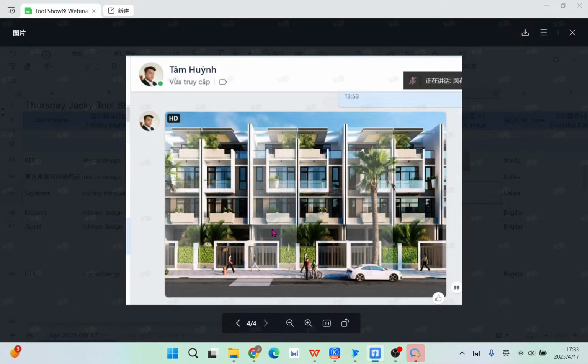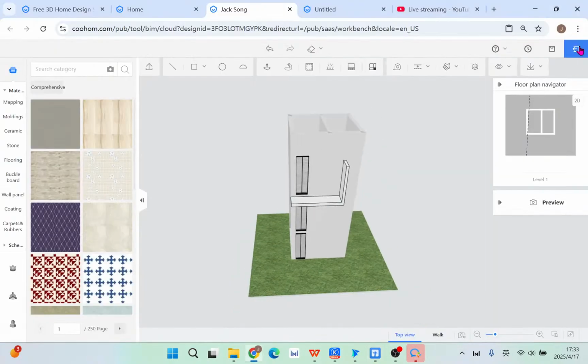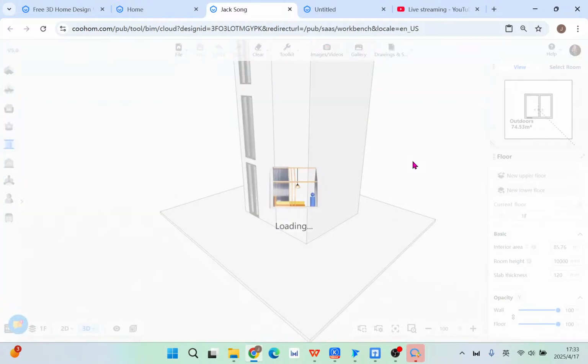Okay, so these are my suggestions. If you see anything that shares the same outer surface, the same elevation, you can mark them as one same floor. And for the different ones, you can use the previous way to set new upper or new lower. So I think here this problem will be solved.